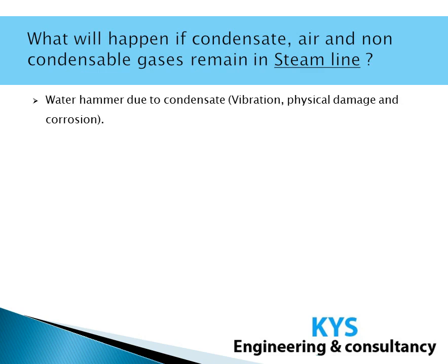First of all, water hammer will start due to condensate, as the pipeline will be having two-phase flow. So vibration, physical damage, and rupture of pipe along with corrosion will start. We will have a reduced heat transfer rate due to condensate mixed in steam.